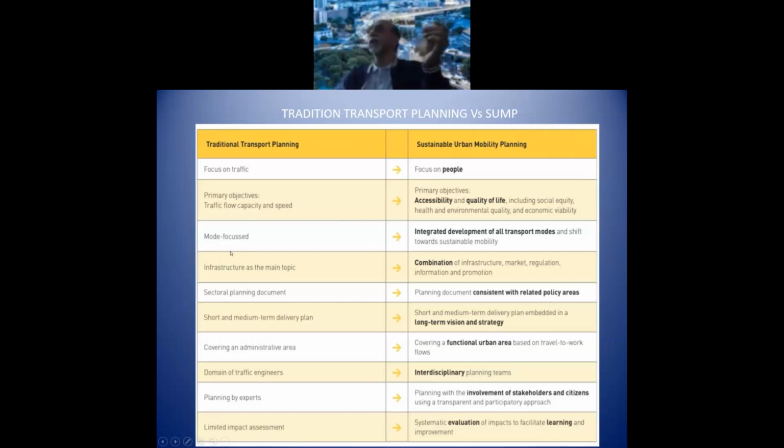We have transport economics and traffic calming devices that are now developed. It is one of the major things in environment because of the sound and pollution that happens due to vehicular traffic. AI is able to correct it in a lot of ways. Today there are these UTC systems which will accept inputs, not just the traffic flow, but will also accept data from the atmospheric detectors, pollution monitoring systems, sound levels. All these are used as inputs for automation or optimization of the systems.